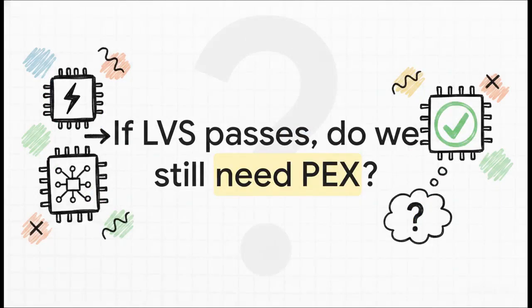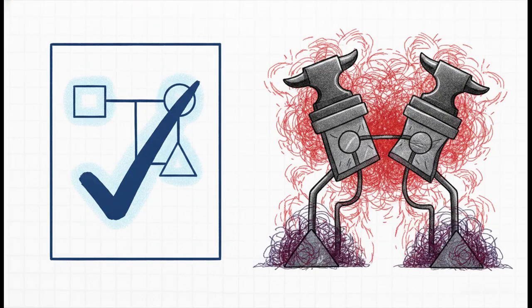So, if an interviewer puts you on the spot, and heads up, this is a very common, very important interview question, they're going to ask you, if LVS passes, do we really still need PEX? Your answer absolutely must be a resounding yes. Look, passing LVS only means you wired it correctly on paper. It literally just confirms connectivity.